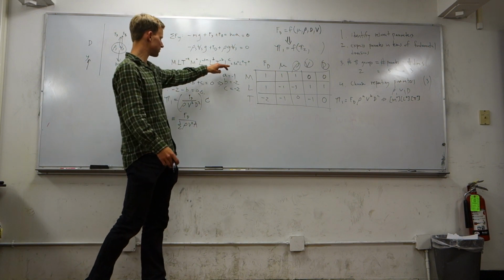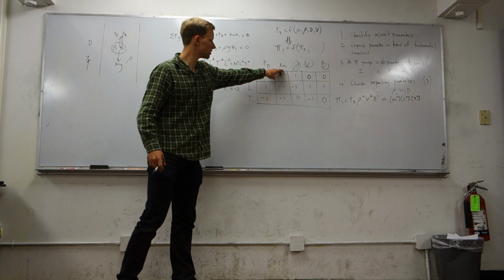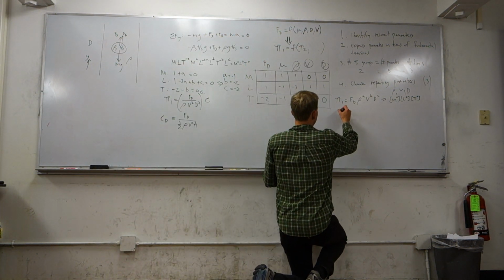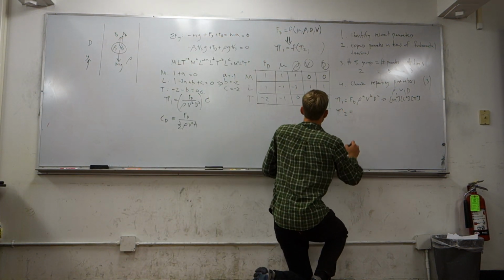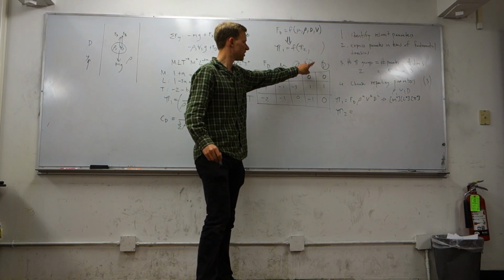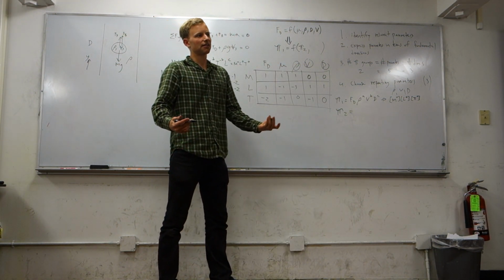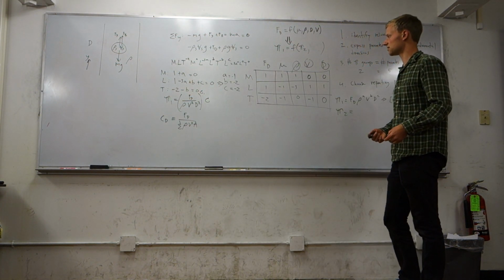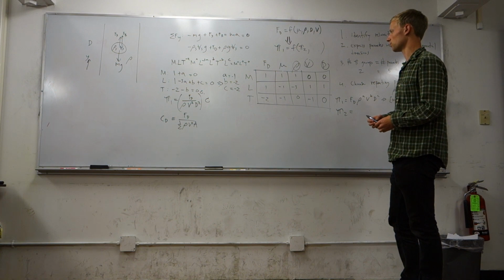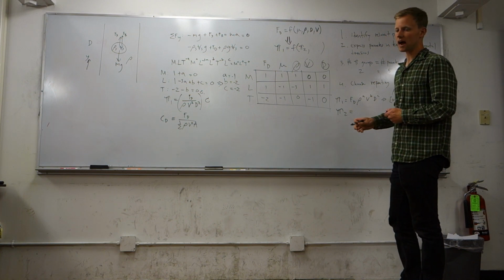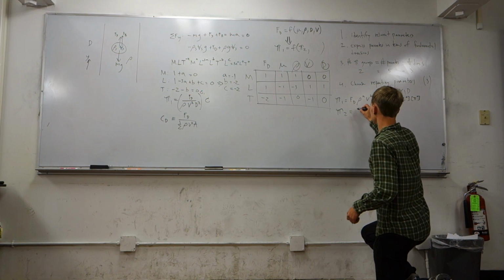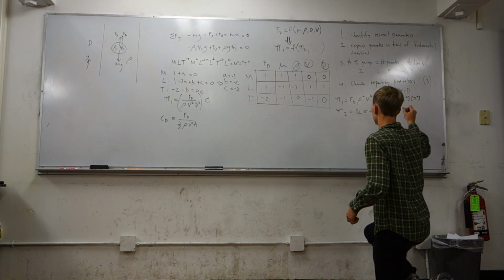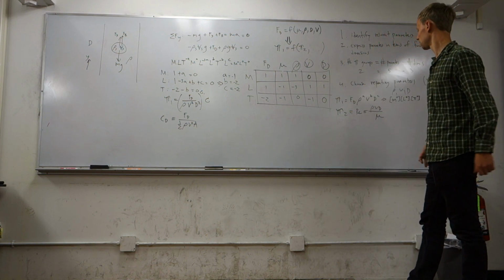We can do the same process for pi 2, just by non-dimensionalizing mu instead of Fd. But we can also recognize something, which is that we have mu, rho, v, and d. And we've seen Reynolds number a bunch of times. By now in the course you should be familiar with what it is and how to recognize it. So we can just pull that right out. We can say pi 2 is equal to Reynolds number, which is defined as rho v d over mu. And you can of course derive this the same way.